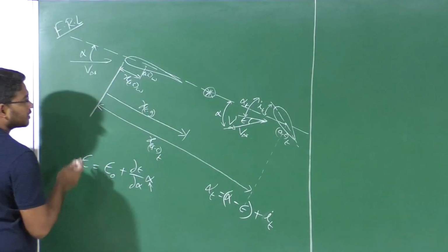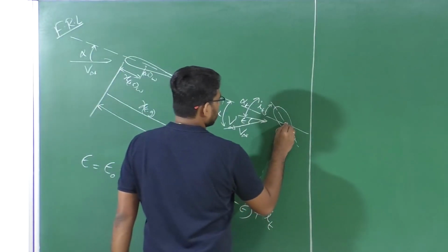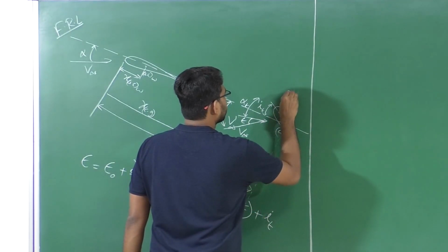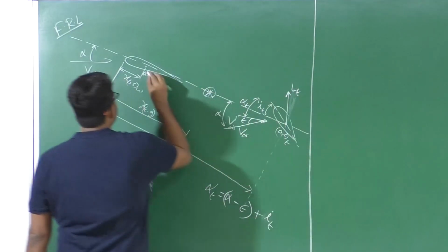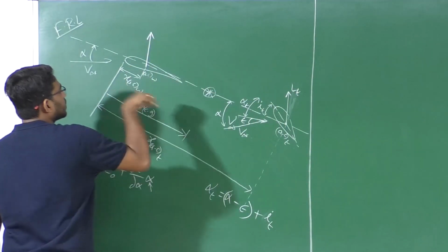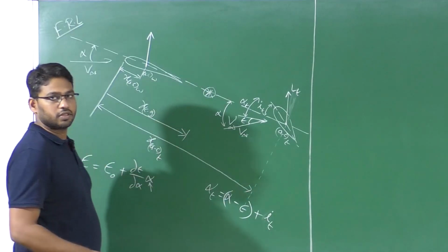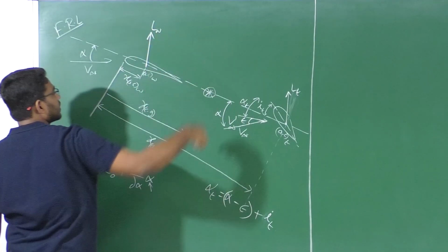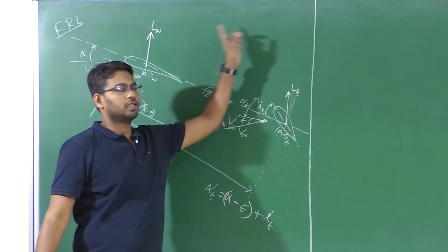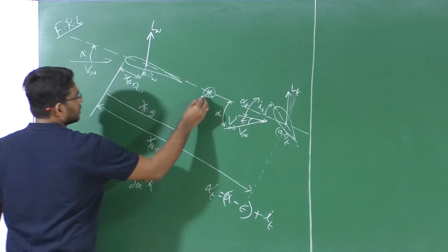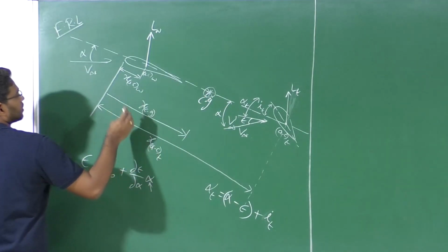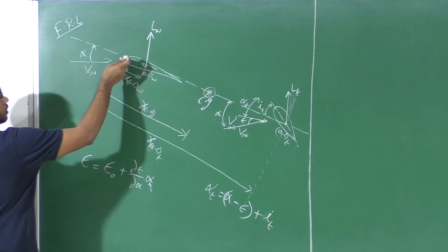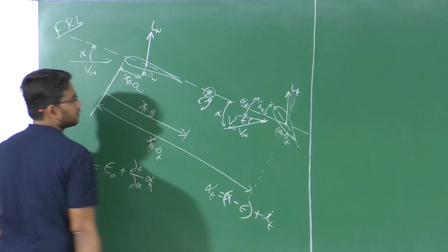And then if you write the total lift equation from here, the lift at the tail will be acting perpendicular to V infinity prime, and we neglected the effect of the horizontal component. Why? Because there is no offset here. And effectively we assumed a small angle of attack, and hence the lift of the wing directly contributes to the positive pitching moment, and the lift of the tail contributes towards negative pitching moment about the CG that we are considering, right? So all these distances are measured with respect to the leading edge of the root chord of the wing, and are parallel to this fuselage reference line.